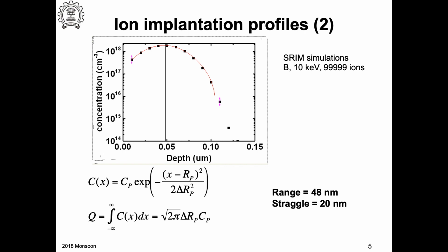Now this is an interesting thing, and lateral straggle is important when I do a mask implant. So if I take a substrate, this is the surface. I'm introducing the ions here. But in fact, I'm not just shooting one ion at a time. I'm actually using a beam. So each of them would actually create a distribution. They will overlap, and then I scan the beam around. So you can see this distribution will overlap.